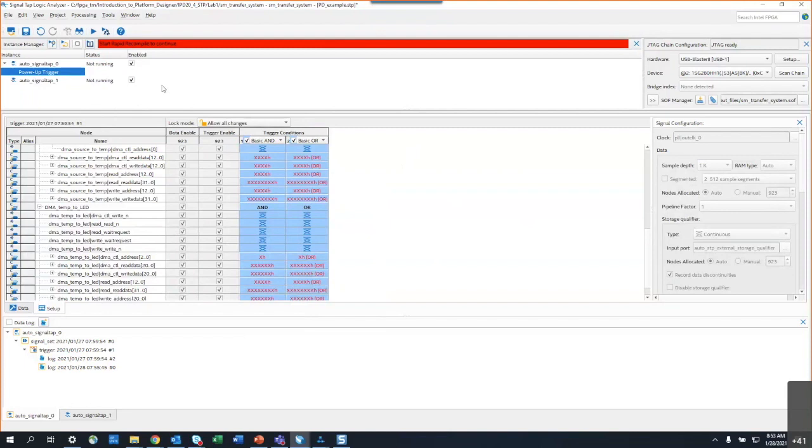And what that means is that one of the issues you might be having when you're trying to debug your design is during reset. You power up your design and it comes out of reset, and then you've got a bug. Normally you cannot look at any signals until you're actually able to come in here and start the logic analyzer. The whole idea behind a power-up trigger is that you want to look at signal activity before you're actually able to come in here and run an analysis.